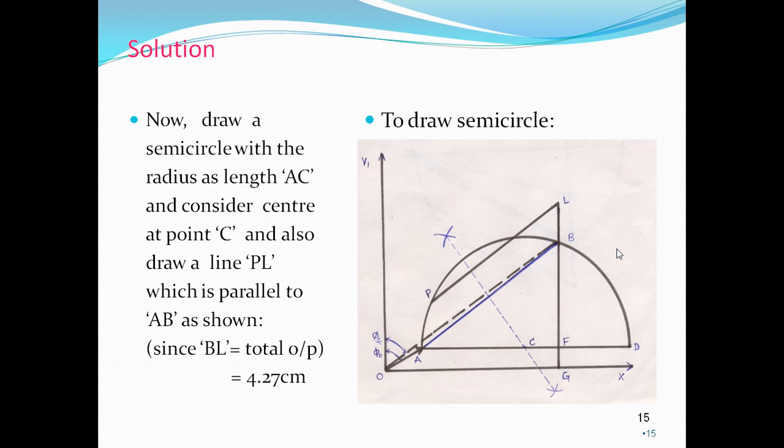After drawing this, we have to extend it. From B you draw a vertical line, and from A also you draw a vertical line. This line from B touches the x-axis at G and AD at F. So BF represents the rotor copper losses and stator copper losses. But in our problem, they have given both losses as equal.